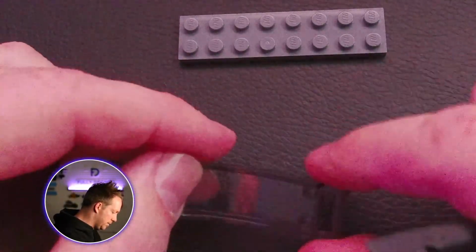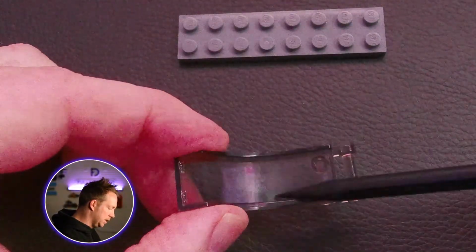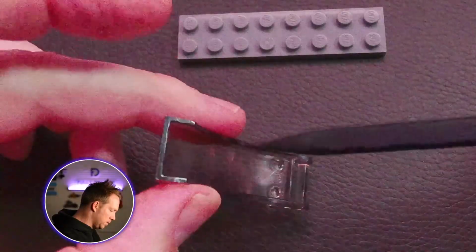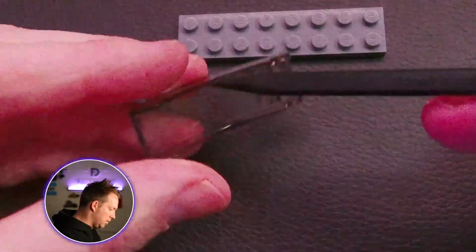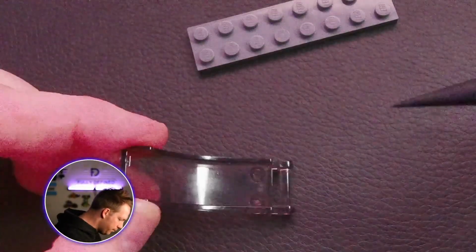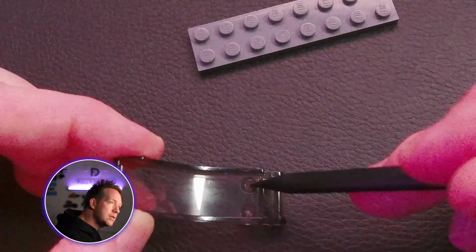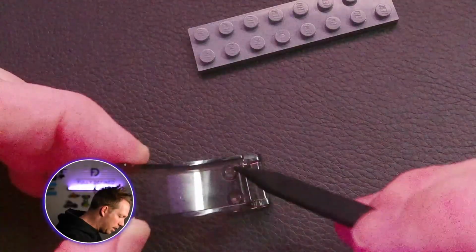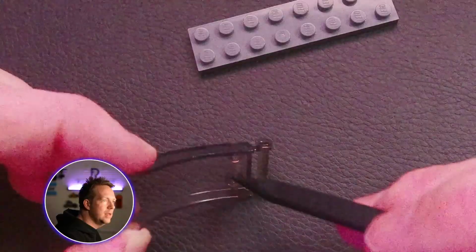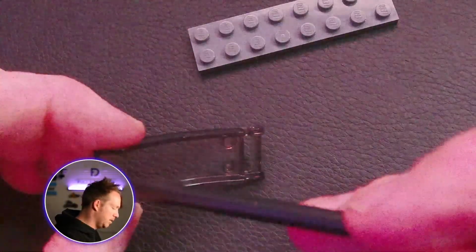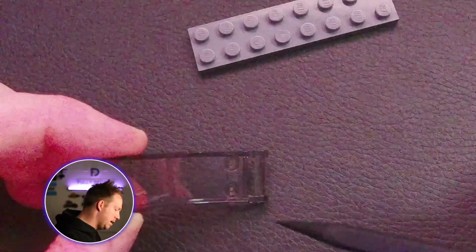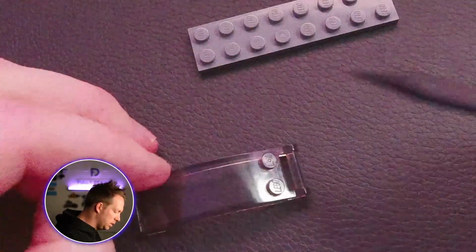CAD-wise, the way to build this, we could build this as a solid and shell out the material, or we could just build the walls and do them individually. We're going to assume that it's got a consistent wall thickness, runs down the middle. We can see that these two little areas here have been hollowed out. Anytime I see a hollow detail like that, it suggests to me that I should use a shell tool because I can remove all of that at the same time. So if this wall is the same thickness, doing the shell will be good.